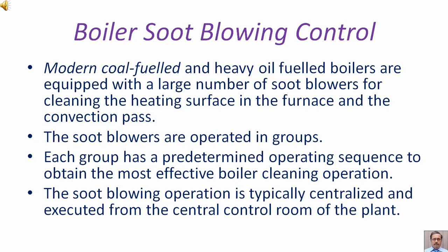Each group has a predetermined operating sequence to obtain the most effective boiler cleaning operation. The soot blowing operation is typically centralized and executed from the central control room of the plant.